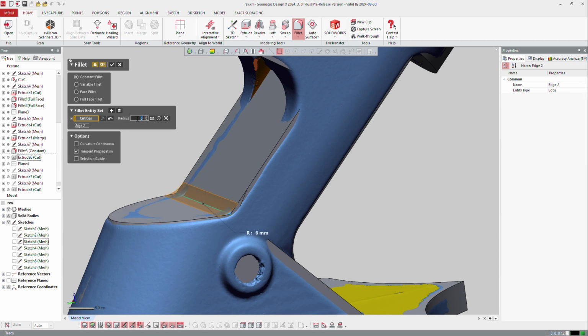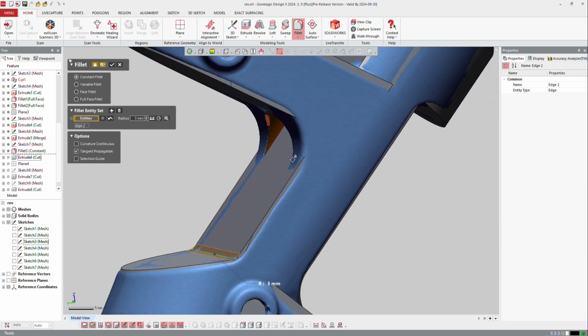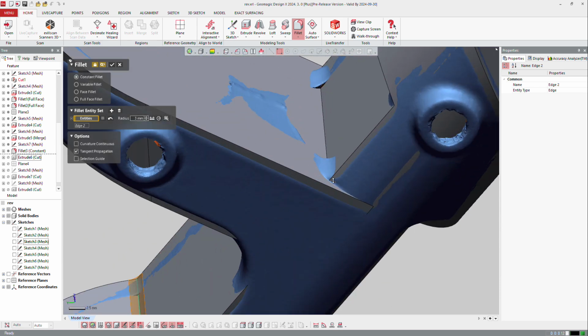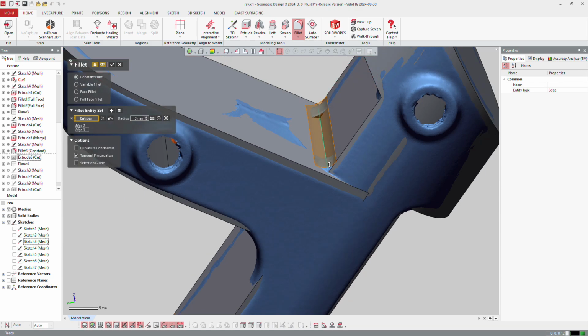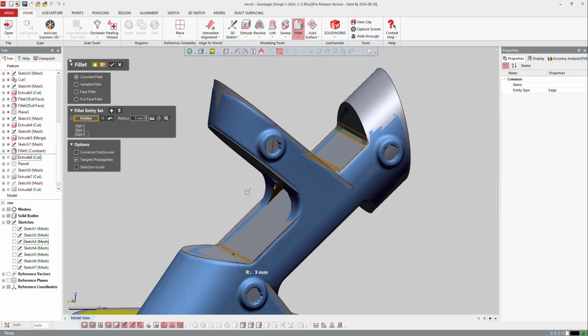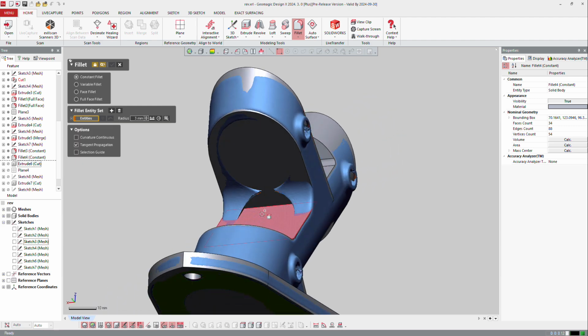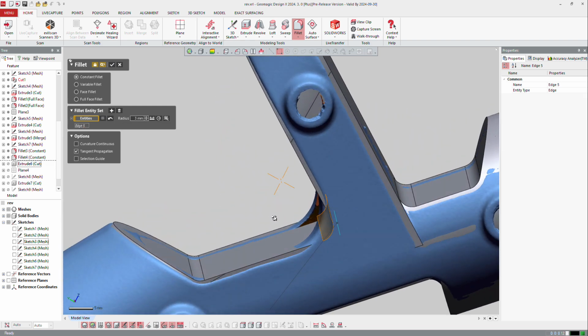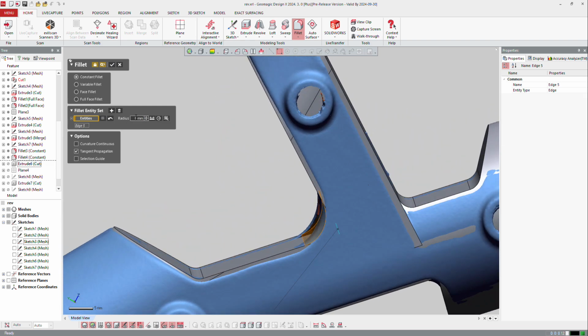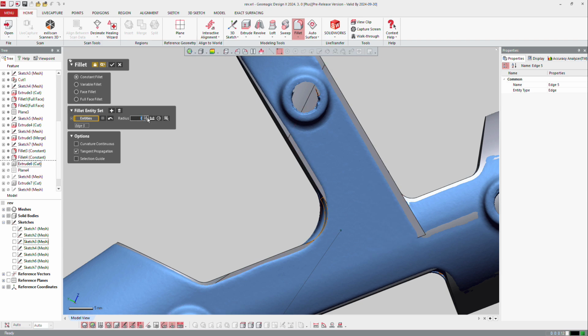Okay, maybe I can also create the fillet on that one. So it should be more 3 millimeters over there. Maybe over there, not on the face, but on the edge. Okay, looks better. And then maybe on all the edges here. And okay. If I want to make that one here, it can be the same. So I can select that, look at the fillet, and again, make it bigger, 6 or 7 or 8. So you can increase here the fillet and check 8 millimeters. Okay.